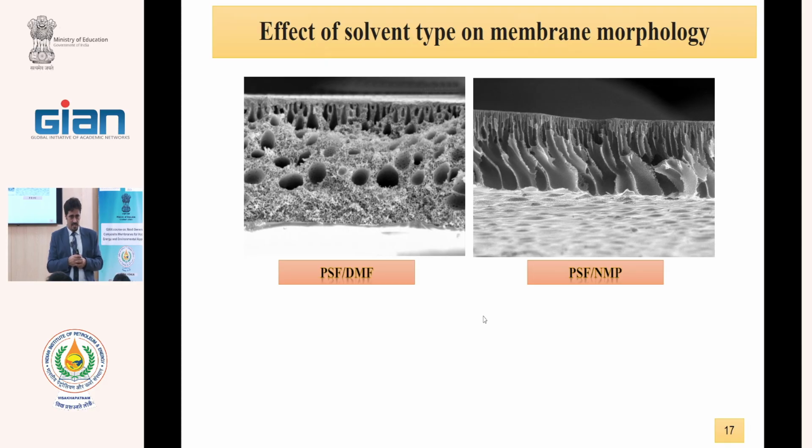For cracks in membranes, we have different methods for reducing them. Defects or cracks reduce the membrane performance. In gas separation, for example, we use polydimethyl siloxane as a defect filling layer. When we produce a polyimide gas separation membrane, maybe because the polyimide is semicrystalline, we may have a defect.